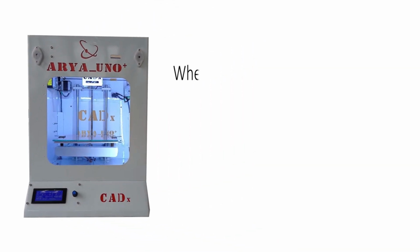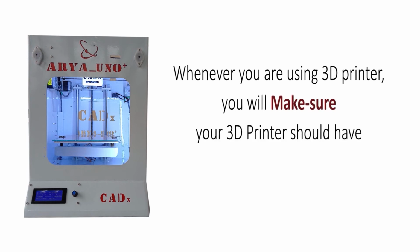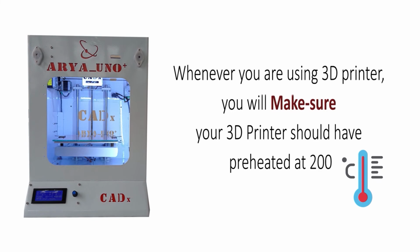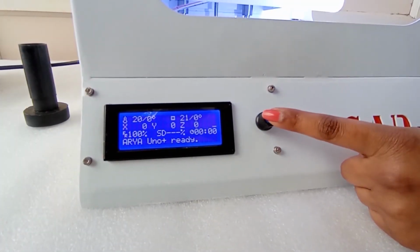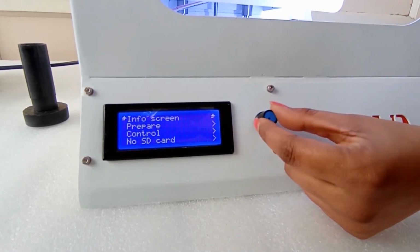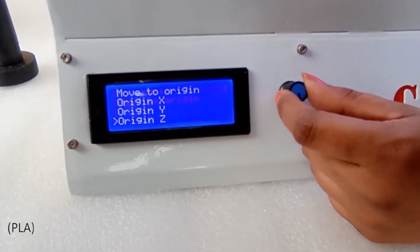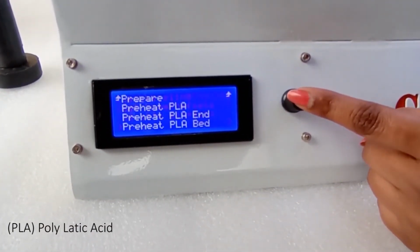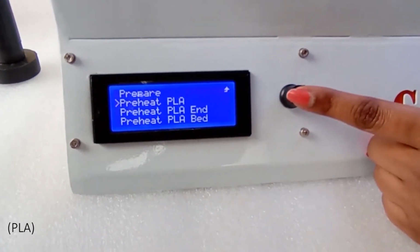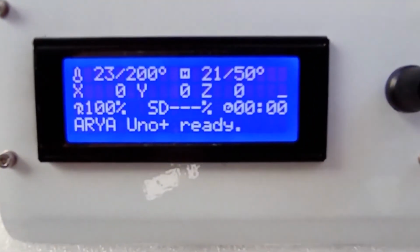Whenever you are using the 3D printer, please make sure that it has been preheated to 200 degrees Celsius. And how do you preheat the printer? Simple. Press the rotary button to switch on. Click on the Prepare option. Go to Preheat PLA. PLA stands for polylactic acid. Click on Preheat PLA. Wait till the nozzle temperature reaches 200 degrees Celsius for PLA.